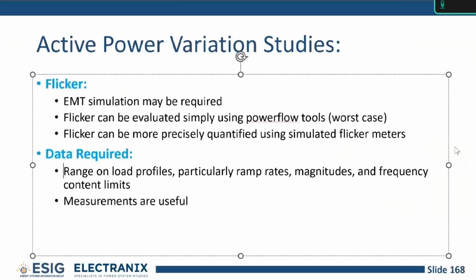I'm curious, there's a lot of customers that don't necessarily know the load profile. Would they even have this kind of information? Well, the nice thing about this study is that if you're just worried about how the voltage change might impact the lights, you can just imagine one voltage change and then say it's going to happen a bunch. So if you just imagine a single square wave or a single step change, you can do a before and after in power flow. So it doesn't really matter what the final load profile looks like. You're just worried about the worst case step, right?